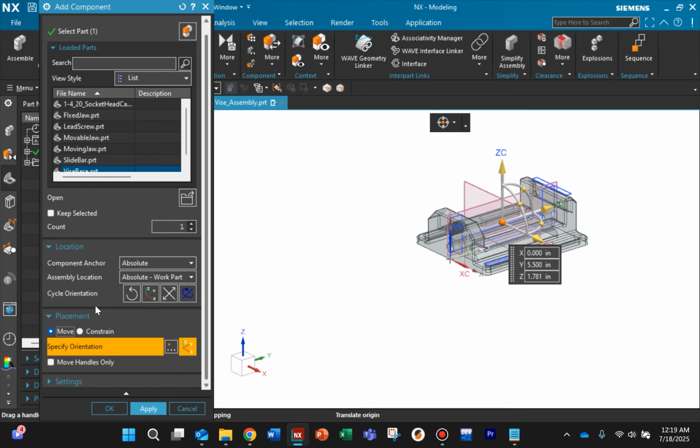So if I have a shaft that's going to be rolling along some bushings, I constrain it so that the shaft can rotate, but not move out of the path of the bushing. So it's going to be located centrally between the bushings, but not allow any movement so that it doesn't move away from the bushings, but it can still rotate. So we can constrain parts to move in certain ways and not in others.